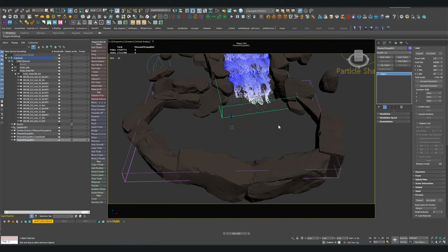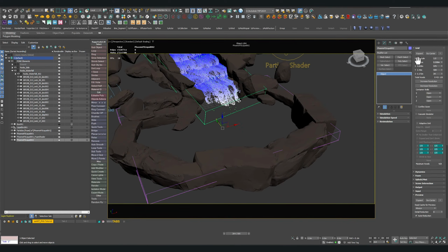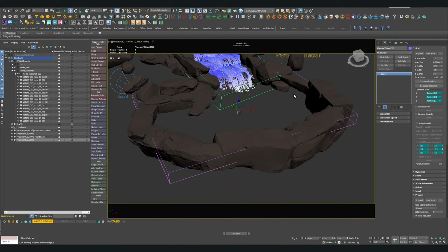So now for the liquid settings, I'm gonna just increase the amount to 8 million particles. That should be good enough. And for our z-axis, I'm gonna go and jam minus. X and Y, we go and jam both sides, which means that the liquid will not get killed, but it will collide with these side walls and with the bottom, but not with the top.